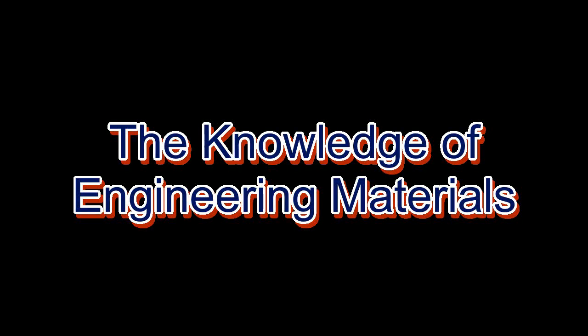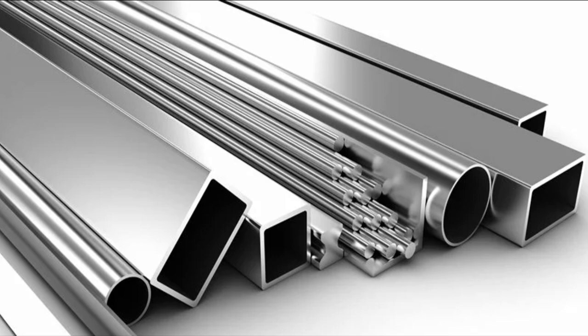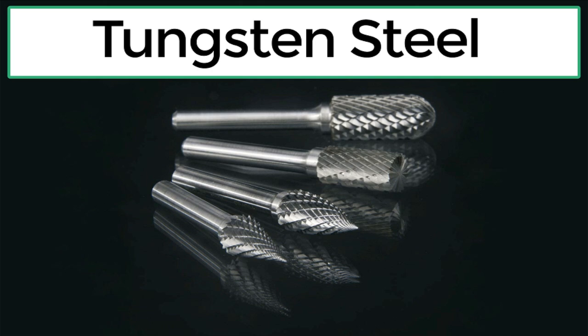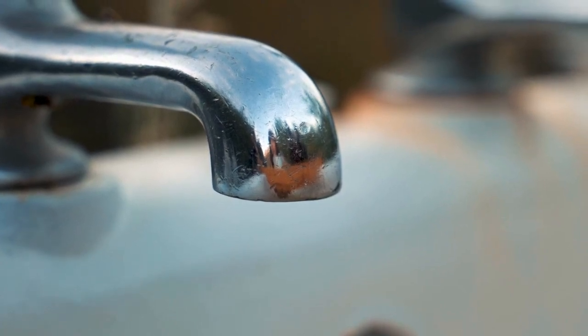The first skill a mechanical design engineer must have is the knowledge of engineering materials. A mechanical design engineer must know which steel grades are to be used in weldments according to the specific application. For example, mild steel to be used for better tensile load bearing. Tungsten steel to be used for high temperature applications. Chromium steel to be used for rust-free applications.